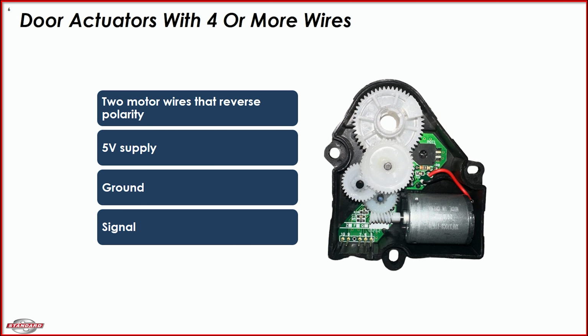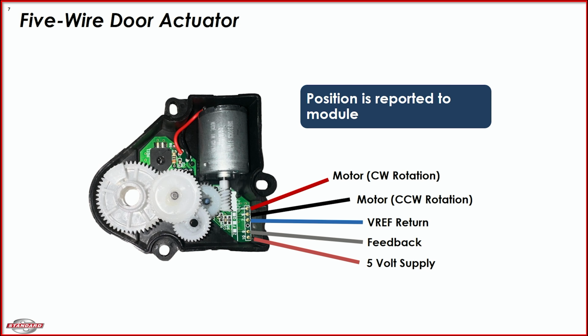Though we don't have a slide for a 3-wire actuator, and just so that you have a point of reference, it has a ground and power wire for bidirectional motor movement, along with a 3rd wire that receives a fluctuating voltage signal to control positional alignment. This voltage fluctuation should not be confused with the higher precision signal feedback that 4 and 5 wire actuators have.